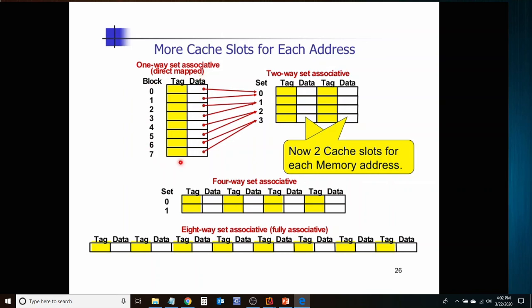This is one extreme. The other extreme is the fully associative cache, where a block may be placed anywhere in the cache. This simply means that we have to search the cache to find out if the block is there or not. This searching is not practical unless we have a very high speed comparator, which means we are going to have extra hardware, and it will result in a costly cache.